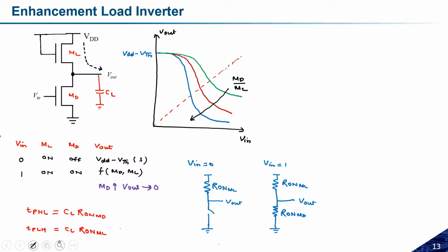So there will be unequal rise time and fall time, a mismatch in the delay component from low to high and high to low. If I have to increase the noise margin, the delay component will be mismatched; they will not be symmetrical. And vice versa, if I have to make the delay component symmetrical, the maximum voltage which we can achieve will be VDD by 2.